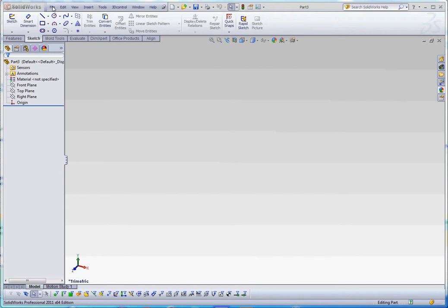First thing you want to do is make sure that you know what your dimensions are going to be. We have 3 dimensions. We have A across the bottom of the T, B, which is the height of the T, and then C is the thickness of the T. So A is going to be, in our example, 75 millimeters. B is going to be 100 millimeters high, and then our thickness is going to be C at 10 millimeters. And length ultimately is going to be 250 millimeters.